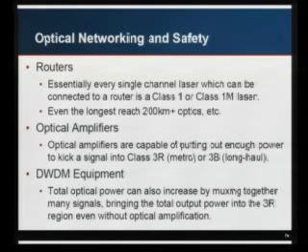What can start to hurt you is when you have optical amplifiers, especially long-haul systems, but even a metro system is capable of putting out enough power that it now officially falls into the 3B category. So don't look into optical amplifiers. And the other thing is don't look into the common fiber, because like I said, if you have what might be a very low-powered system times 40 now becomes a very high-powered system. So generally speaking, if you don't know, don't look. In reality you can't see it anyways because it's infrared.